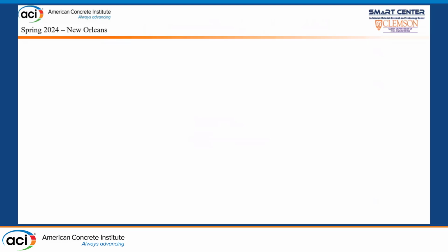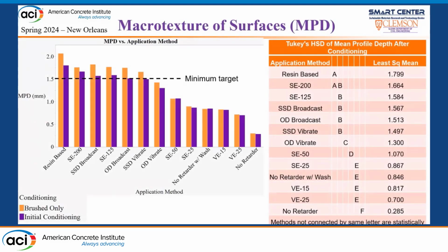We also completed British pendulum test results for this section, but they were very comparable, and most met that threshold of 70 BPN, so I didn't include it just to be succinct today.